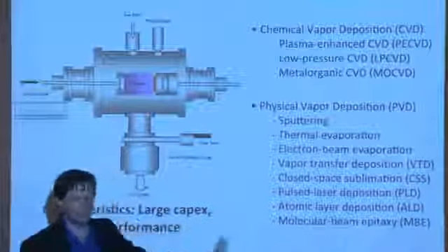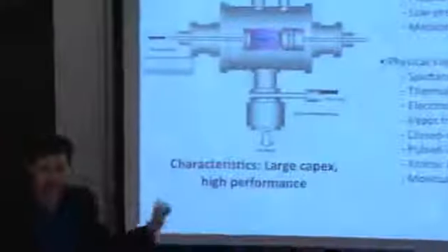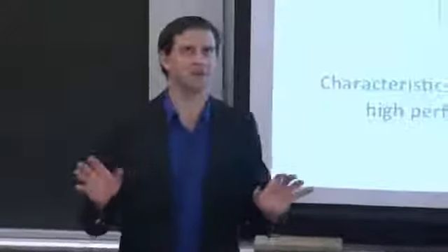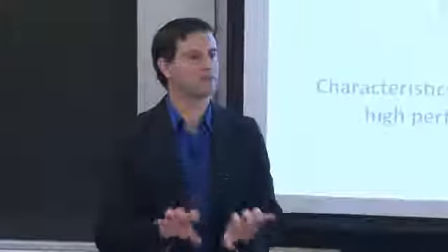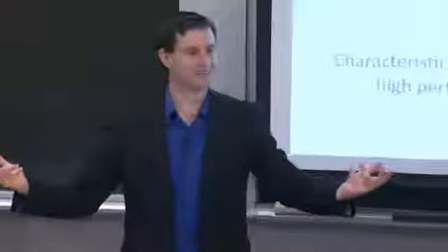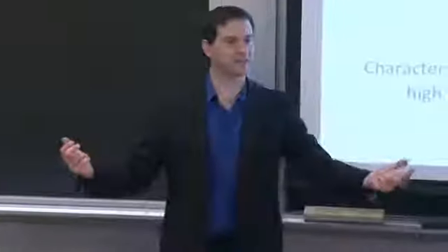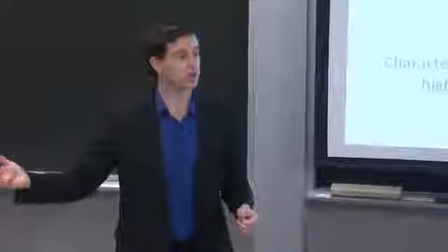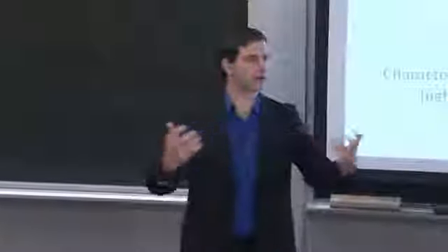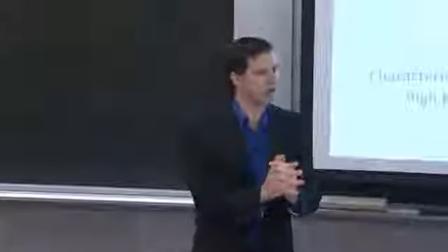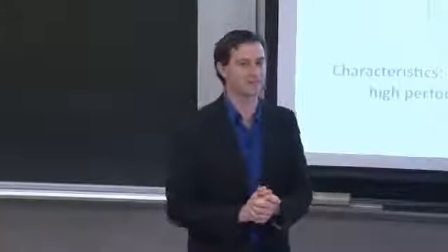And so a very simple way to think about the vacuum-based deposition technologies is a compromise. It is an oversimplification indeed, but it's an easy way to get started thinking about the parameter space of all these techniques. It's a compromise between speed and quality. Some of the techniques that are fastest also tend to be the lowest quality materials, and the ones that tend to be the slowest tend to produce the highest quality materials. How do you optimize somewhere in between, somewhere in that parameter space, to get reasonably high quality material, just enough that you can produce a high efficiency device?